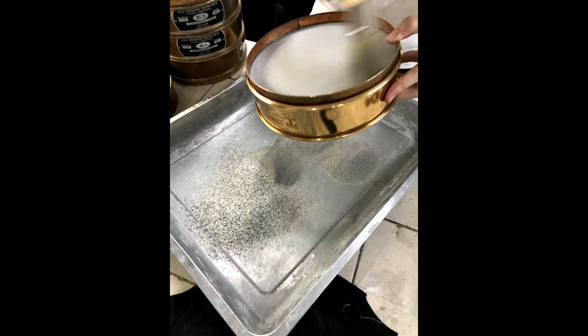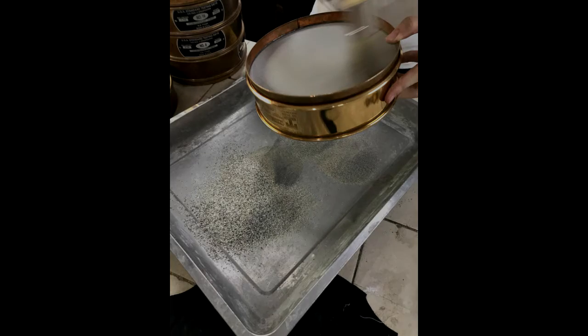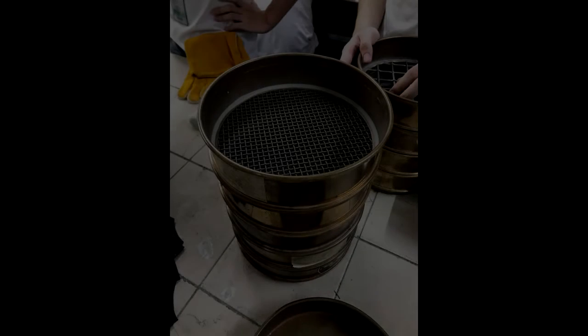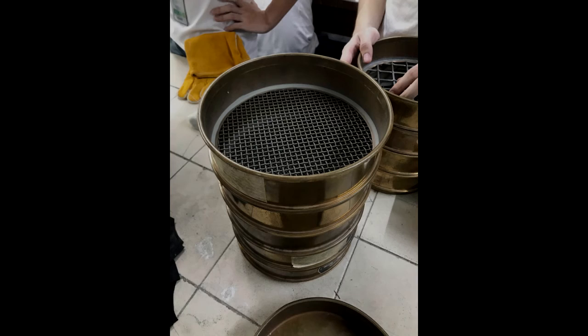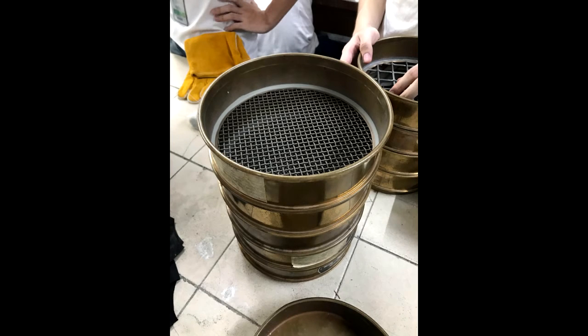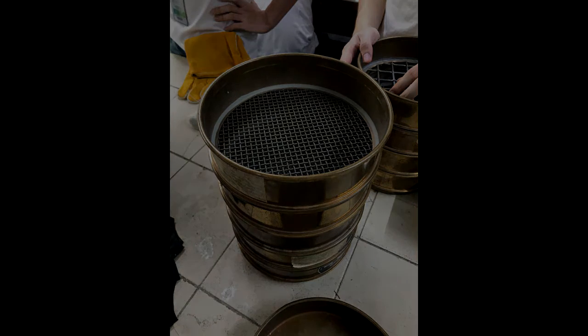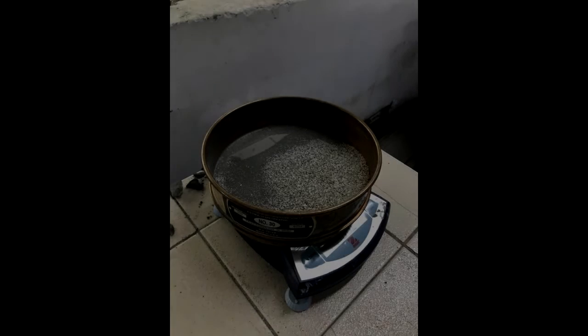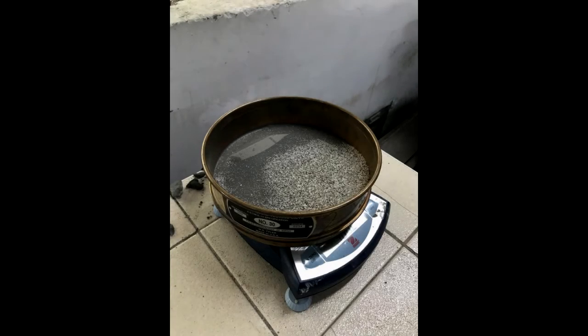For the procedures, after weighing the collected samples for both fine and coarse aggregates, the sieves were organized from the largest to the smallest size. Then, the samples were poured on the sieves and placed in the mechanical shaker for 2 minutes, so that the particles would automatically fall. Then, each sieve was shaken manually in order to have more accurate data, and to make sure that the samples are thoroughly sieved. Finally, each sieve was weighed in order to obtain the amount retained in that particular sieve.